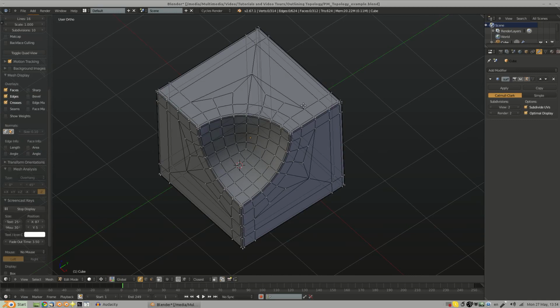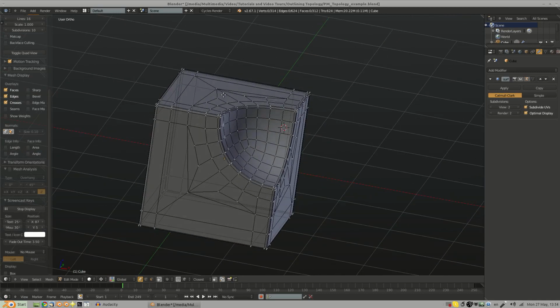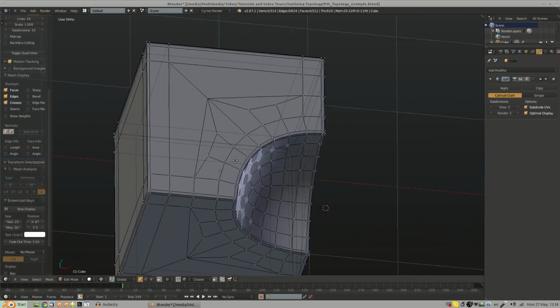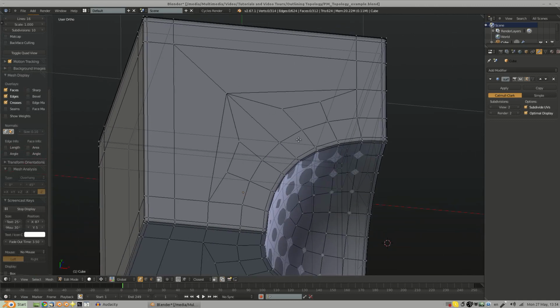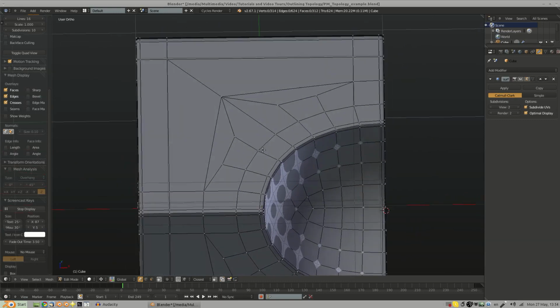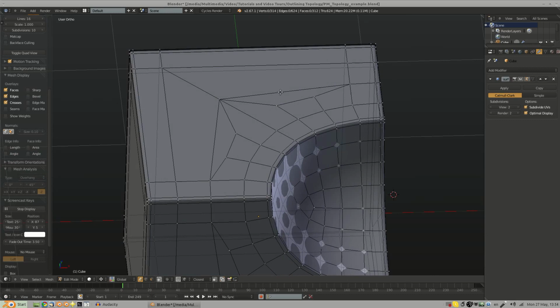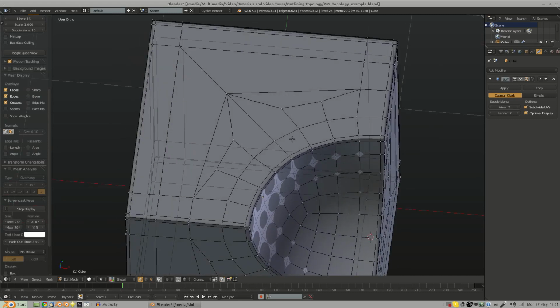making the rest of it fit around it, because especially with flat surfaces, like in this case, this little trick here of rerouting around to simplify topology going down, this really only works with flat surfaces. So for instance, on a car, you could basically use this on maybe a car's door or on the boot lid, but not on the wheel arch or anything that's curved, because it will show up.